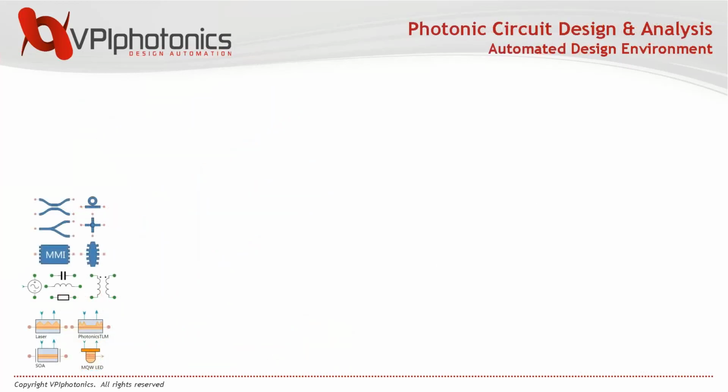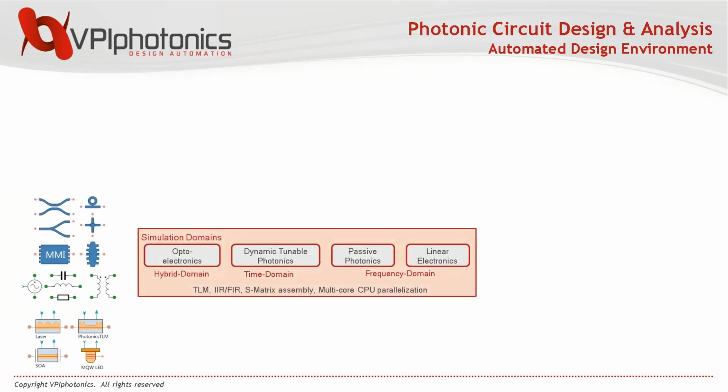So when we talk about dedicated software, what do we mean? Talking about circuit level simulator, first of all, it is surely some library of building blocks, so you can combine them to create your passive circuits or multi-sectional semiconductor lasers, for example. And in addition to these circuit components, there are also components for analysis, and also a huge number of application examples.